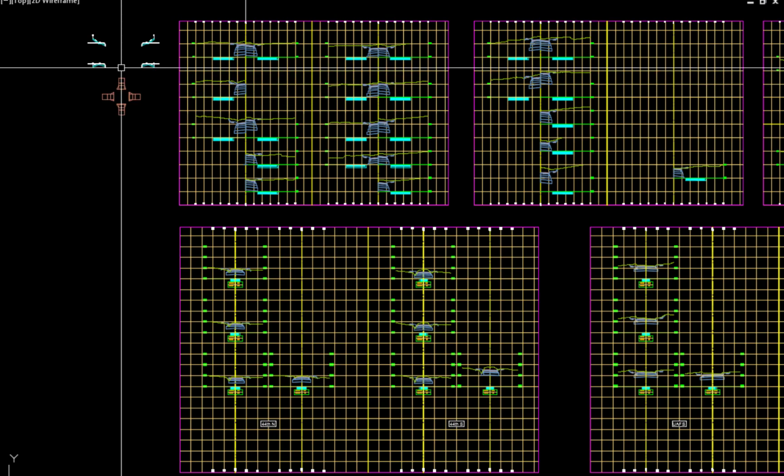Escape to stop the command. The driveway templates contain 4 profile templates and 4 plan templates. The profile template contains 2 templates for the left side of the road, 2 templates for the right side, 2 templates for the upslope driveways, and 2 templates for the downslope. The plan templates contain a driveway in each cardinal direction: up, down, left, and right.